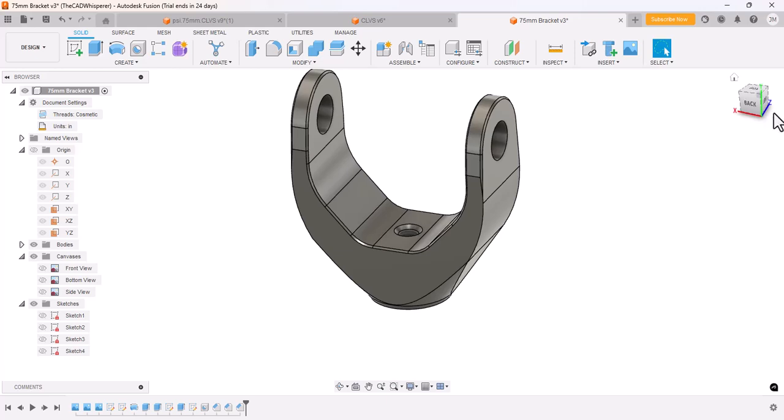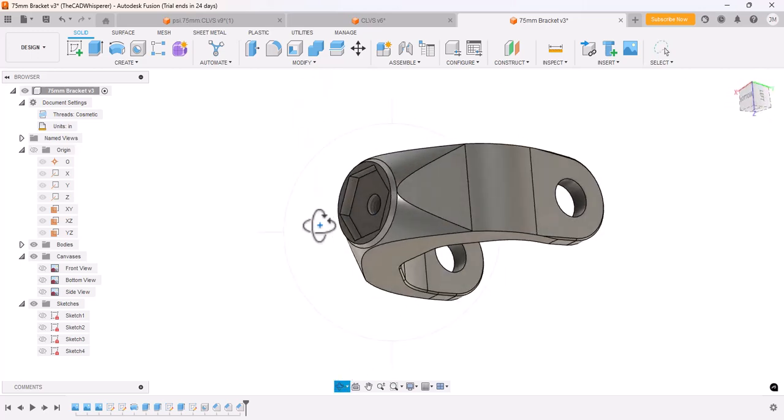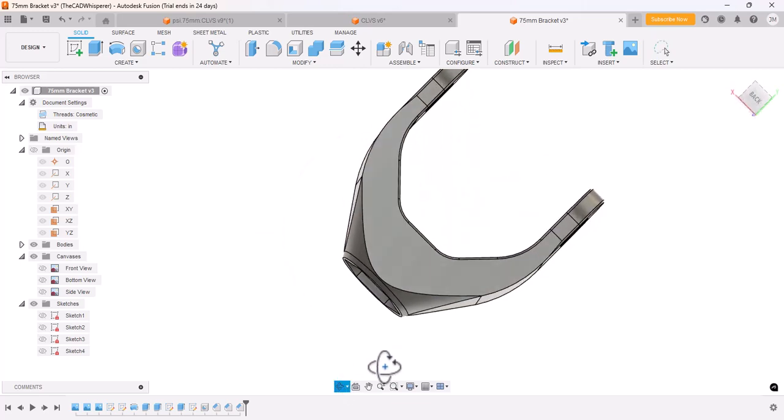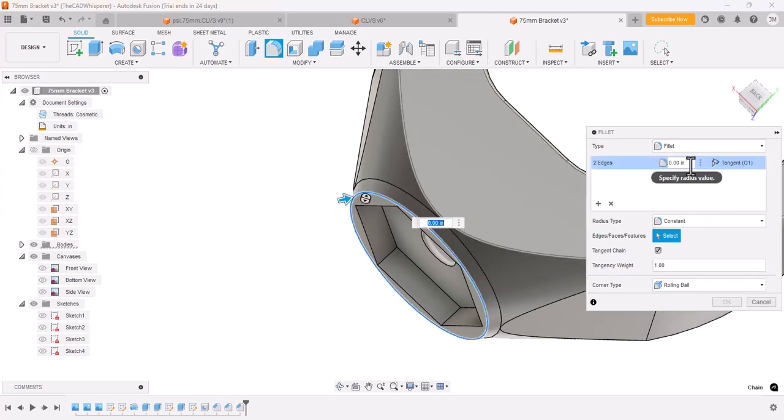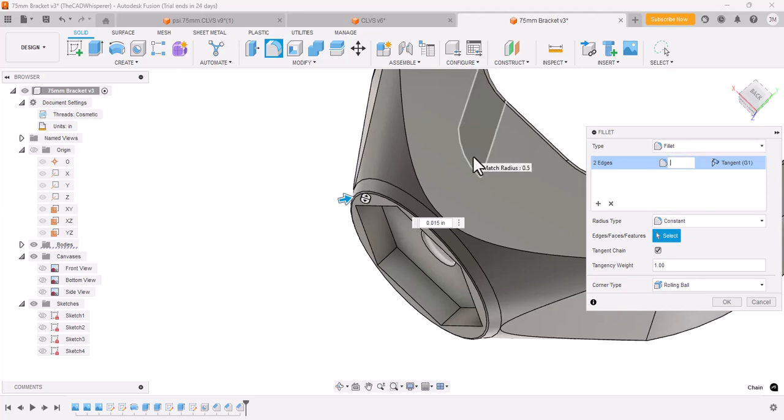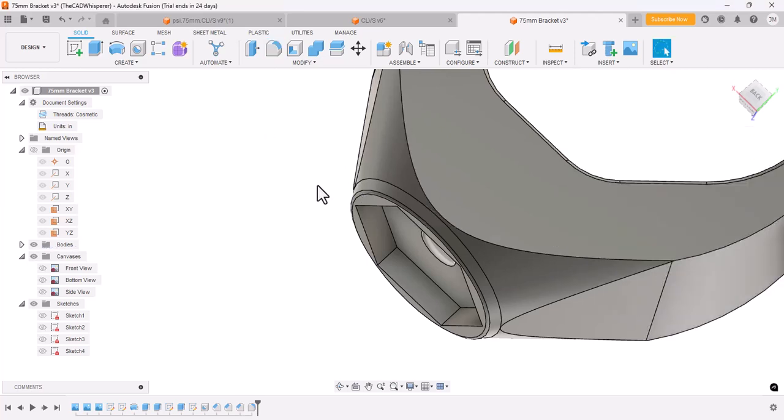And then there's a chamfer down on the bottom side. Let's look at that. So let's rotate this part back around. Chamfer on this threaded hole. And so let's look at that. Did I ever put the fillet on here too? I don't think I ever put the fillet. Okay, so let's do that fillet. I forget what it was. I'll do 0.015. We can always increase it. Let's do 0.03. Check the drawing. Make sure you match the drawing or whatever it's supposed to be.